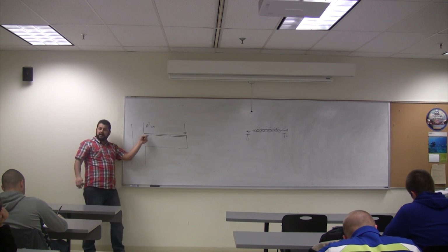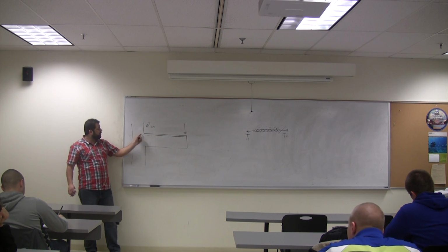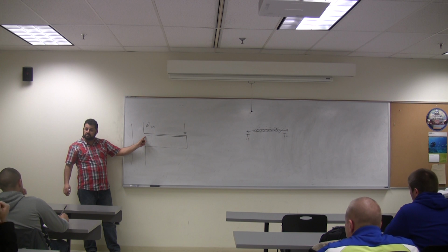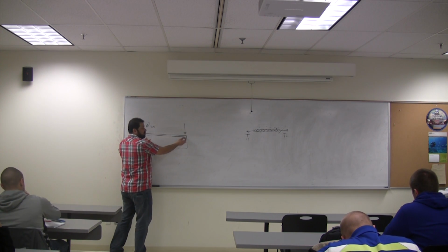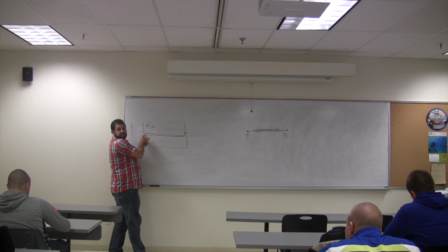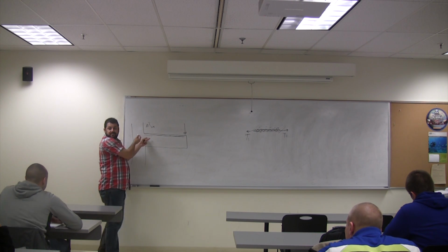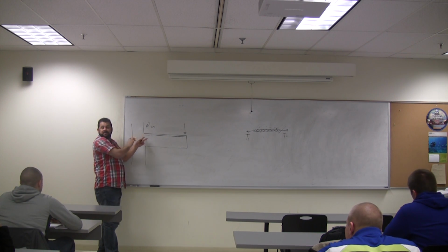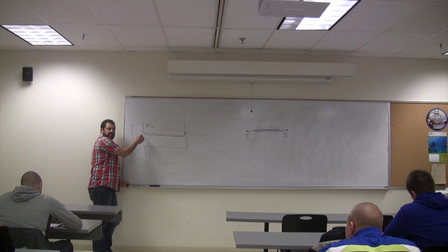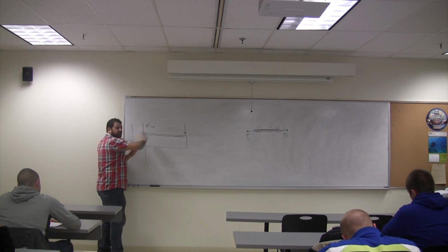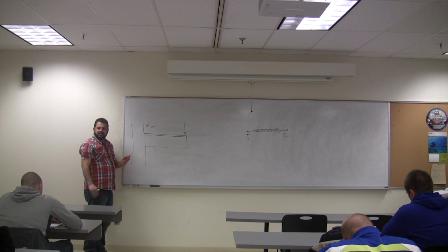These bars are supposed to give you a Fy here. So you can say, oh no, but they do that, because if I go from this way, it's good. What if I go from this way, where these bars are supposed to give me a Fy? Do we agree about this one here? They must develop a Fy here. To the right and to the left, they must have enough development length.